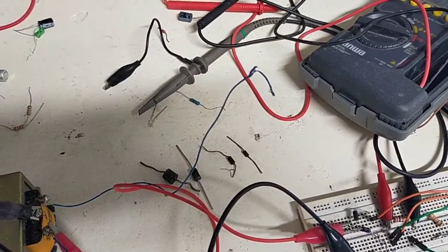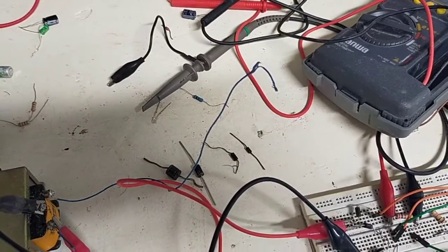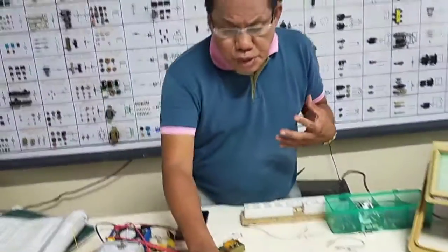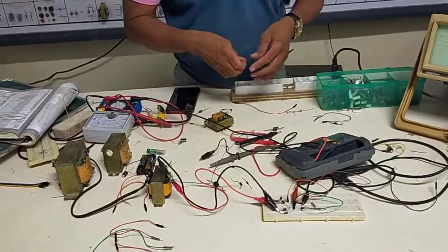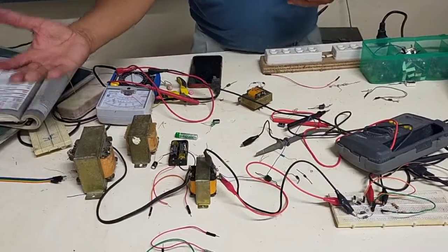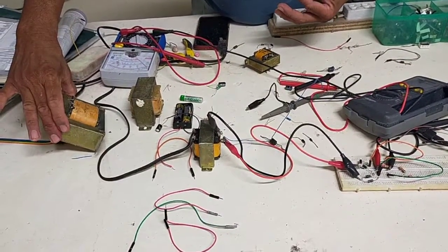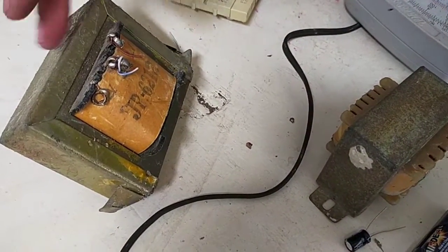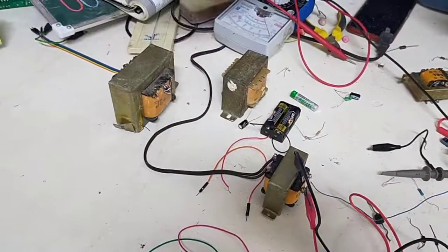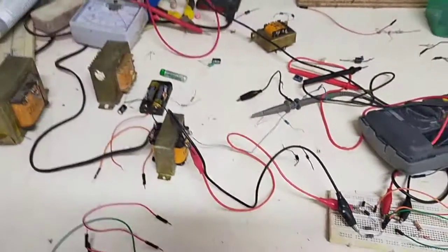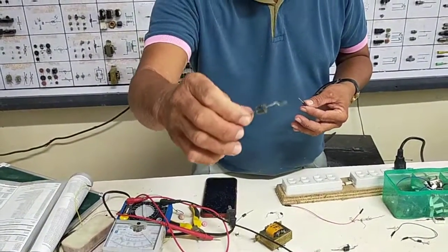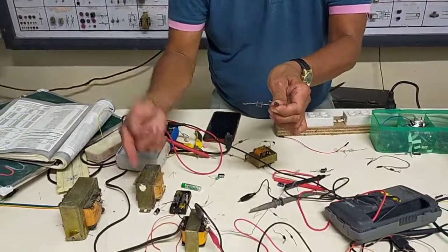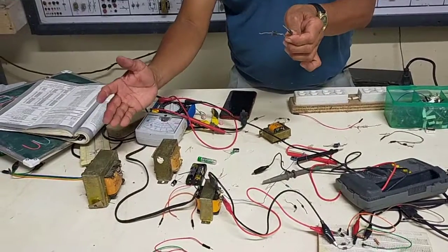The maximum current rate of a diode is 30 amperes based on this diode manual. Now, that is the maximum forward current. When do we use this current rate, the physical size? If you are using a bigger transformer, for example, this transformer is 6 amperes, the appropriate diode that you are going to use is a 6 amperes diode also. Because a 6 amperes diode can handle the intensity of the current distributed by this transformer, which is 6 amperes.